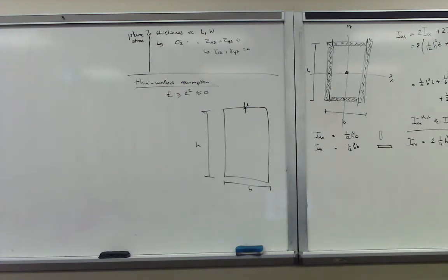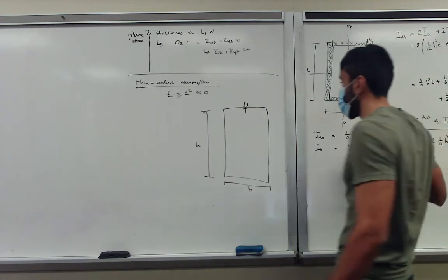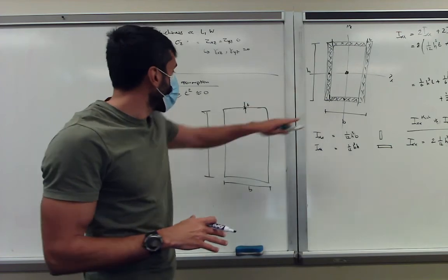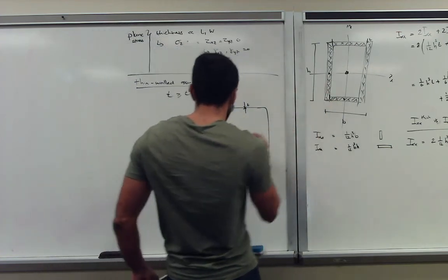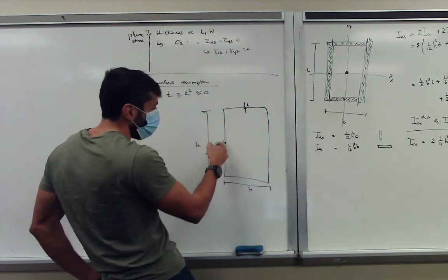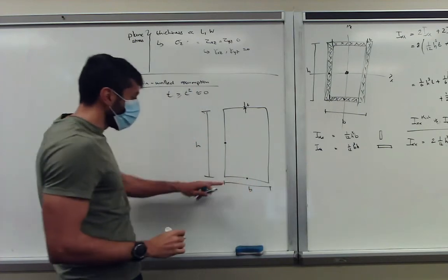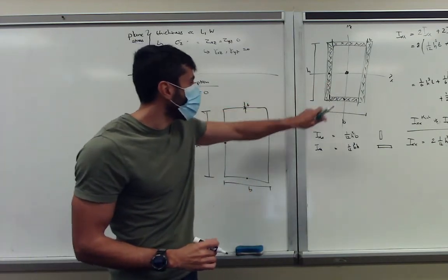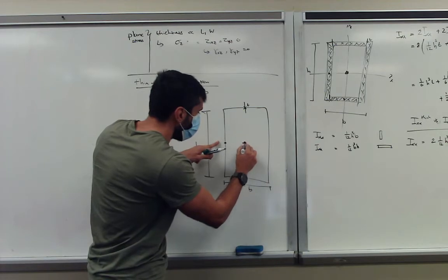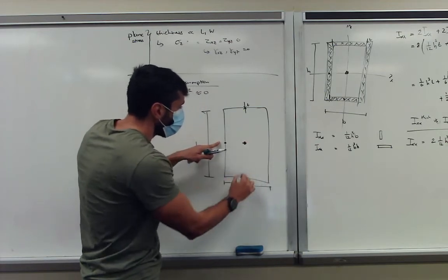So we basically reduce the complexity of our equation, and then what we get is something like this. Instead of having to deal with the expansion of the equations, probably I've made a mistake in the expansion, so you can double check that on your own. But what we do is we basically reduce this component to a thin wall. So we assume that the centroid of this top part lies on the thickness itself as well, so we no longer take into account the thickness effect. We just say the difference from the centroidal axis to this given coordinate system, or local centroid, is just the distance of h over 2.